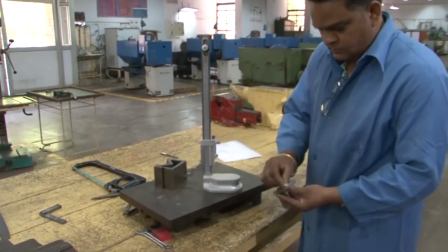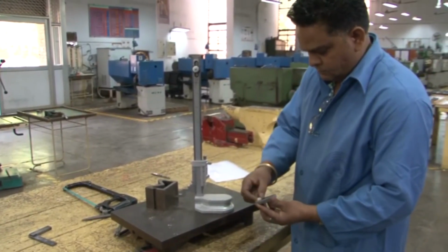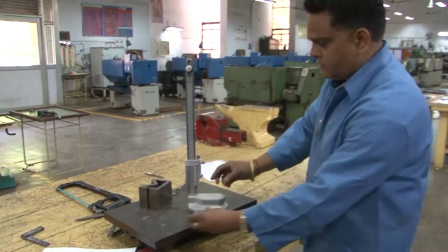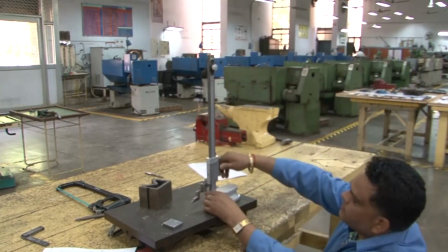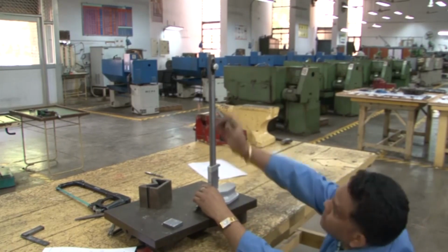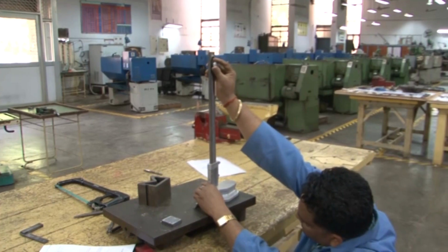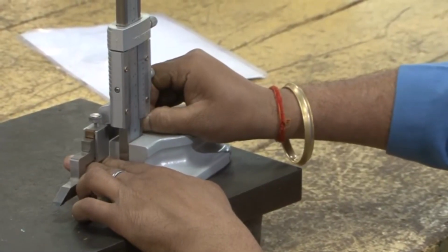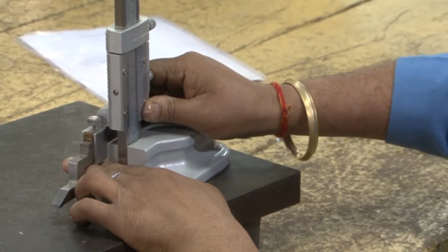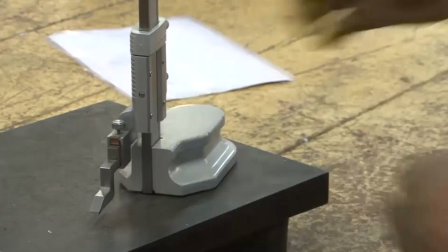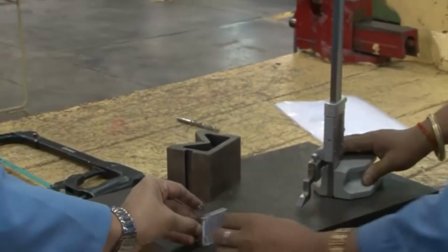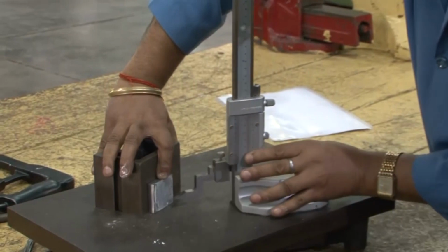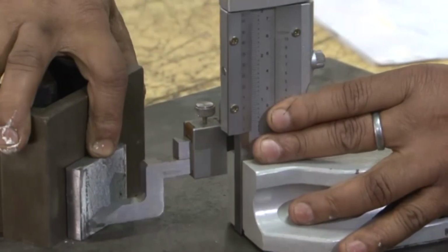Okay, now it will be marked. As I was telling, there will be some kind of painting, or you can even use chalk for that, so that the marking will be visible. You can also use a white paint, so that it could be visible prominently. Now, this is the height gauge. This is the 0 position, and then according to the requirement in the drawing, at which height you have to have the hole from one of the bases, either from here or from here, accordingly you have to make the marking. So, that it is 10 millimeter. You set 10 millimeter in the height gauge and you just make the marking.